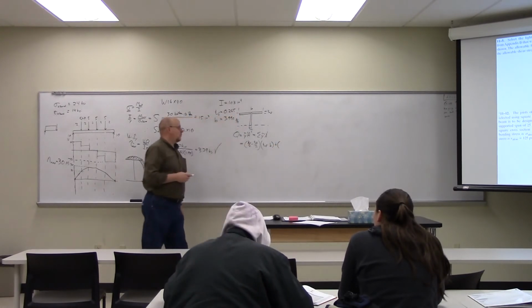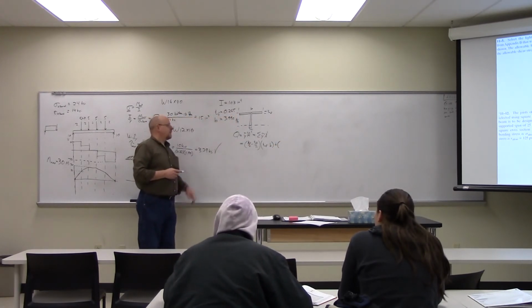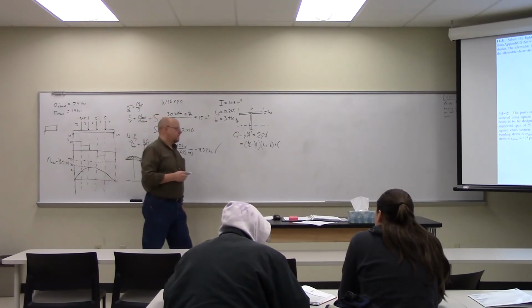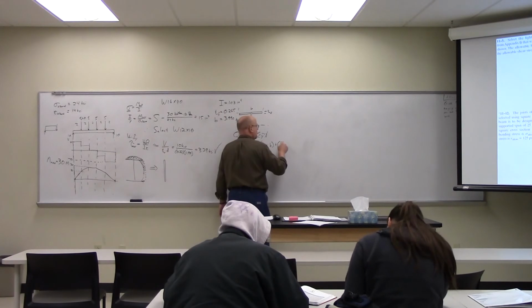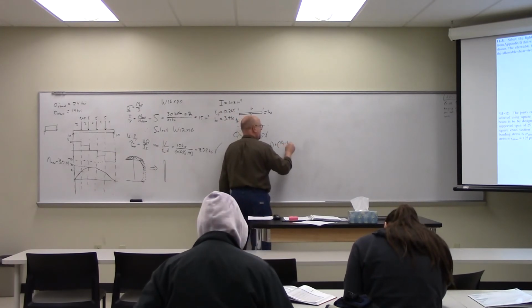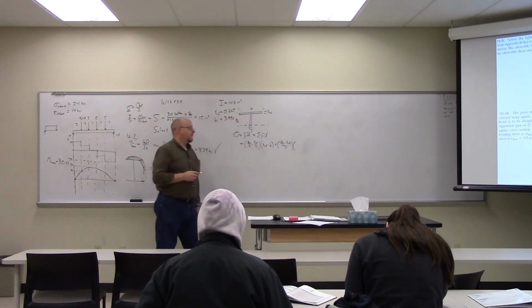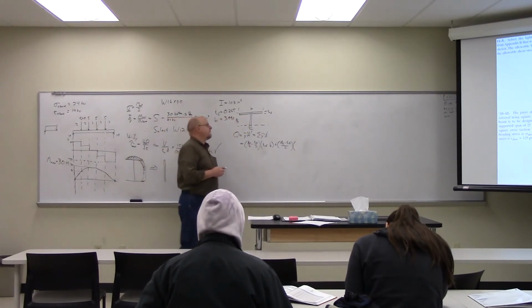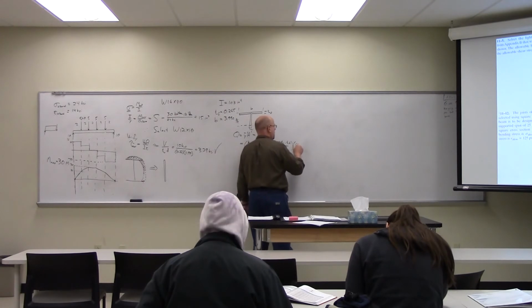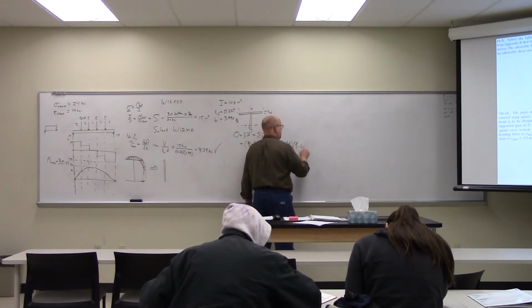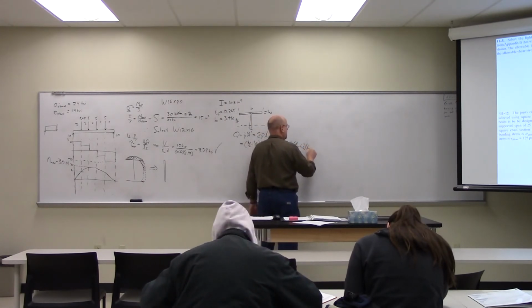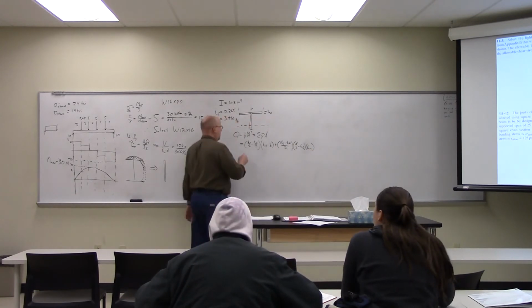Okay, for the second one, what is the Y tilde? D over 2 minus TF divided by 2. And the area? TW times D over 2 minus TF. D over 2 minus TF times TW, right? So let's go through and figure out what those are.